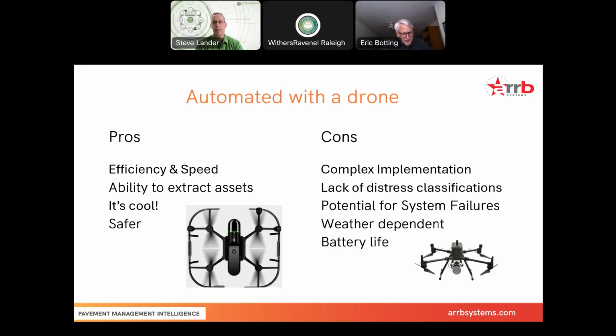Let's see, I always tell them to send me your best picture, and when they do, you can't see the surface defects, the oxidation, the ravel, you can't see it. So again, as it matures, hey, if you could have a drone flying behind traffic at a lower level, so you can get those defects. Maybe you put a better camera on it, and the one on the right has lidar. So then that brings all of the advantages that lidar brings to it, which is a certain amount of automation for feature extraction that you're trying to get to.